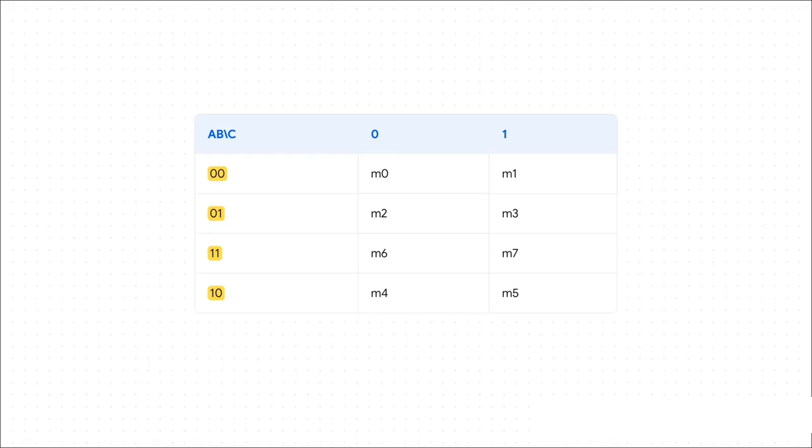And here it is, our empty game board. This is a 3-variable K-map. See how variables A and B run down the side, defining the rows, and variable C is up top for the columns. Every single one of these little squares corresponds to one of those minterm positions, from 0 all the way to 7.